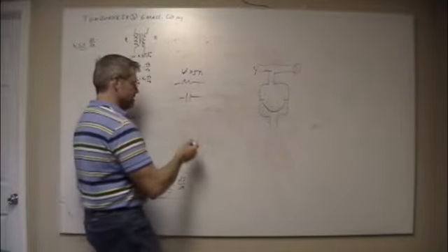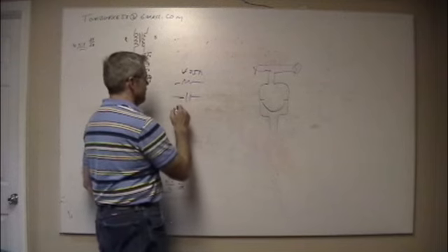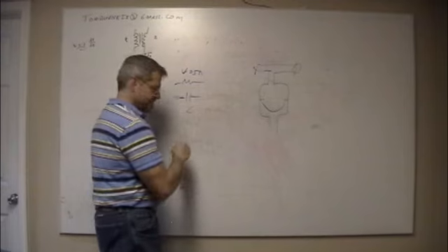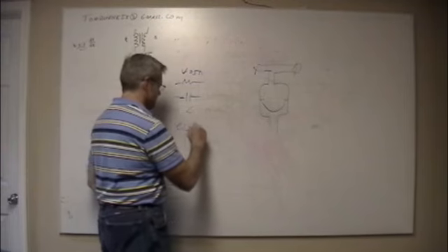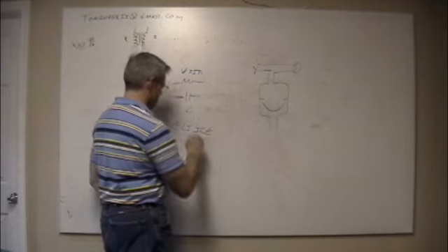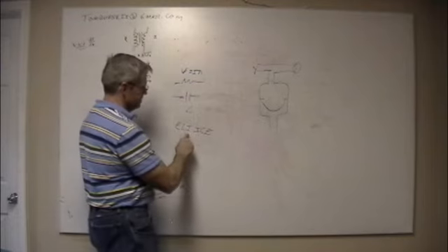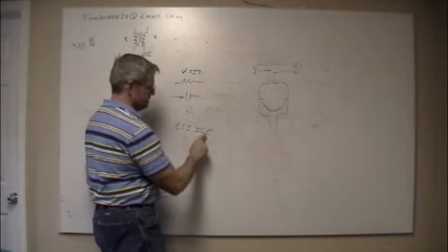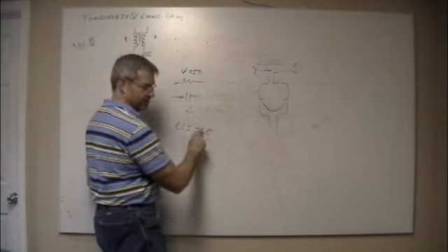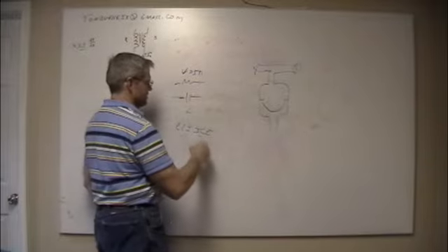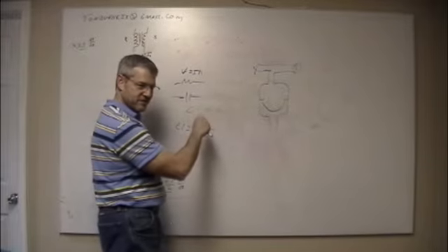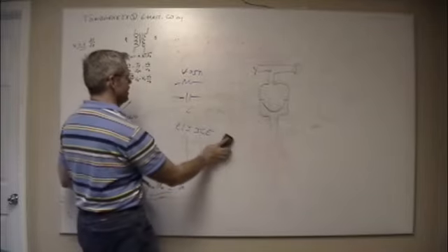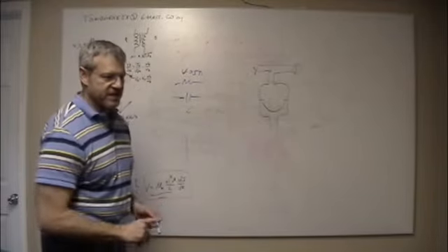And that frequency dependence, you start talking about phasors, because ELI the ICE man: voltage leads current in an inductor, and current leads voltage in a capacitor. Because of all these same things, right? He looks like a dead short to high frequency stuff. As soon as that edge comes in, the current goes through. And so you start talking about phase angles.